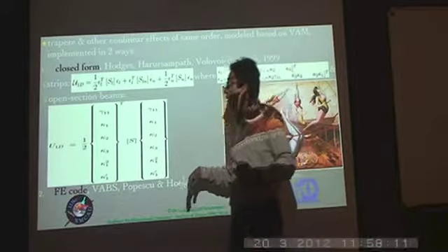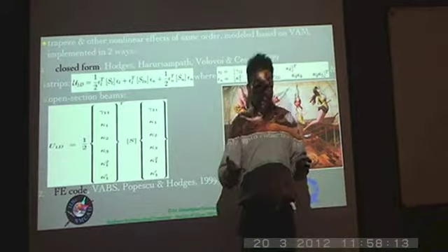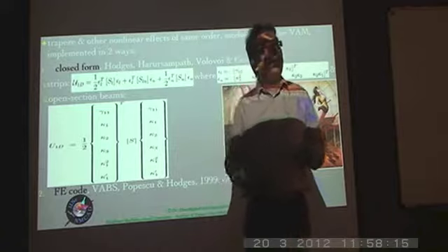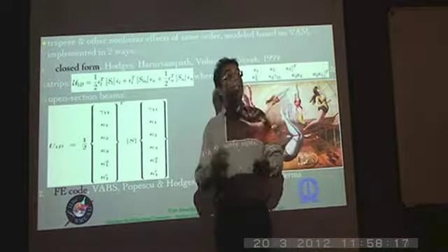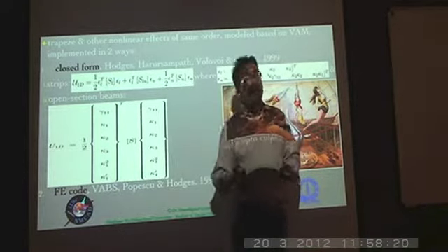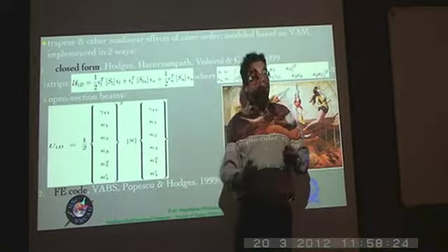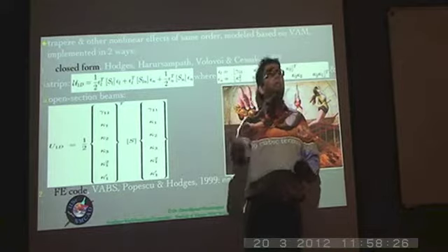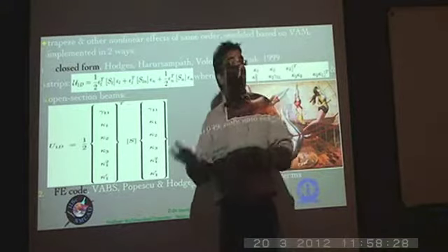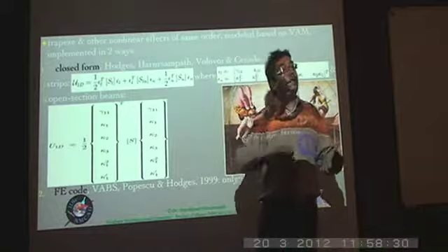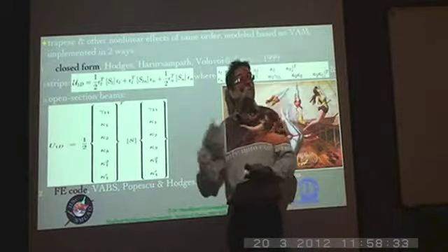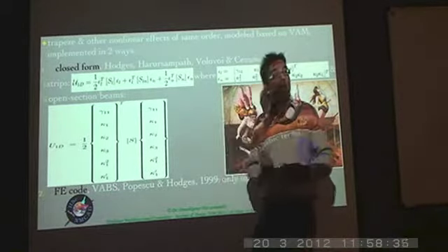So what basically happens is that the only thing that is small in terms of the diagonal elements of the stiffness matrix is the GJ, or the torsional stiffness, or GJ equivalent for a composite material. So the torsional curvatures are large, and therefore the nonlinearity is due to the torsional curvature, and of course their cross connection with any of the other 1D strains becomes dominant.